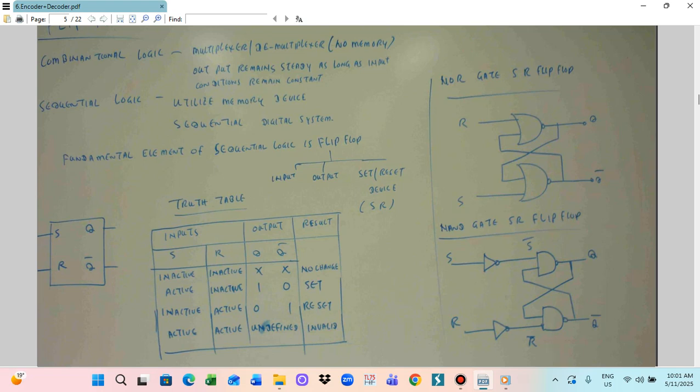Especially we can utilize it for a flashing light. Flashing light means 0 and 1 are changing. So long as you put the set, the output is a flip-flop like this. But when you want to stop, you have to put a reset. So this is why we use the flip-flop IC. Especially we use the flip-flop for the timer, divider or the counter.